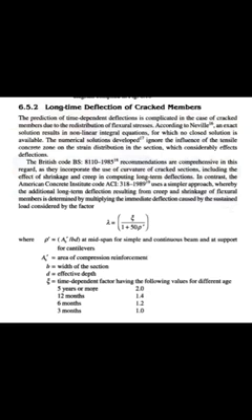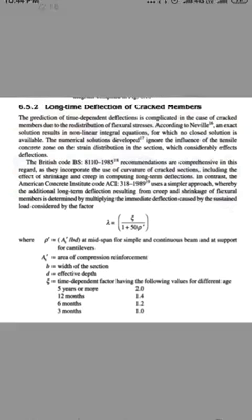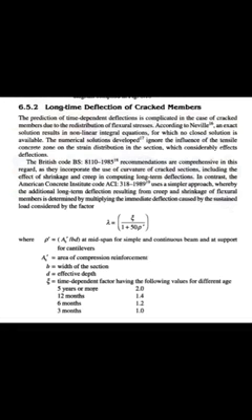According to Neville, there is no exact solution for the nonlinear cracked section, and it involves integral equations for which there are no closed-form solutions available for the long-term deflection of the cracked section. Here a numerical solution has been developed for the tensile concrete zone on the strain distribution of the section, which has a considerable effect on the deflections.